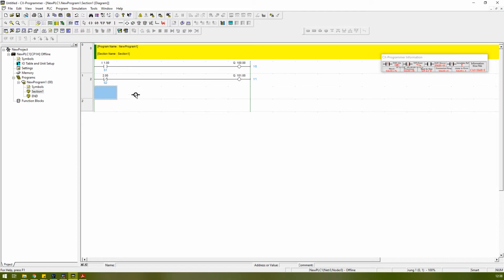Right, if you have connections that are not interconnected with another circuit, you need to put them inside the new tab here. So you can see here, this is step 0, this is step 1, and this is step 2. After you finish designing in one tab, another tab will automatically appear. Right now we have already finished our simple design inside CX Programmer, and we want to simulate. To simulate, you can just click at the simulations and click at the work online simulator.